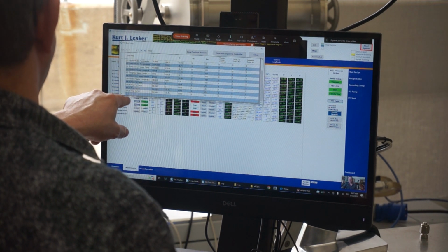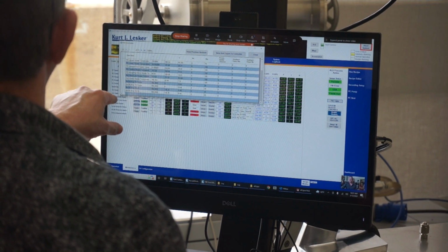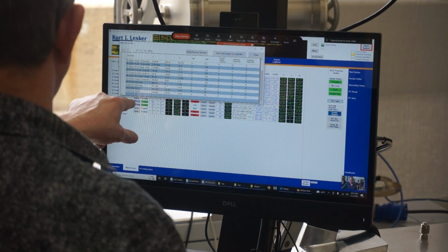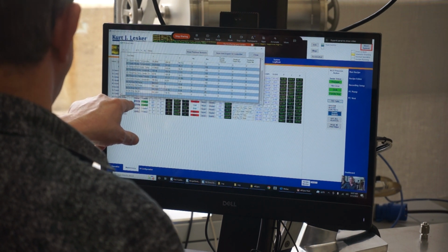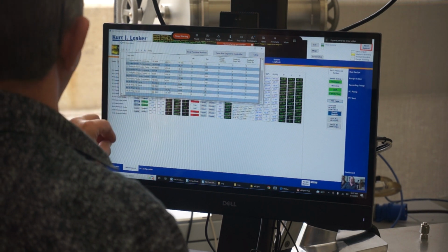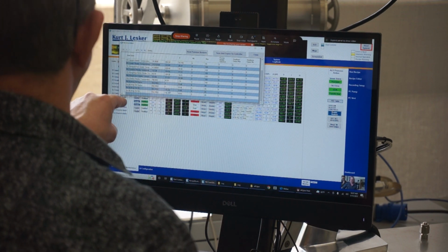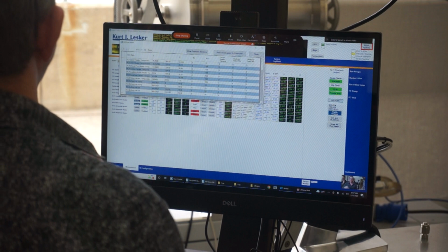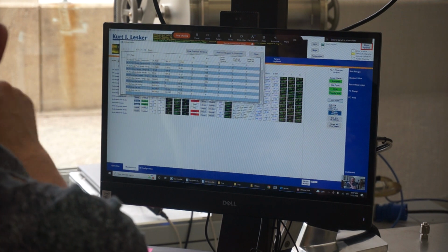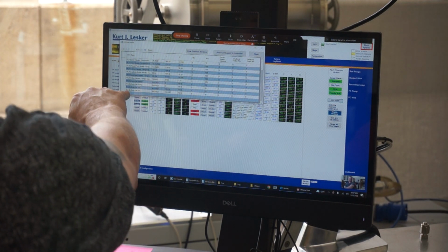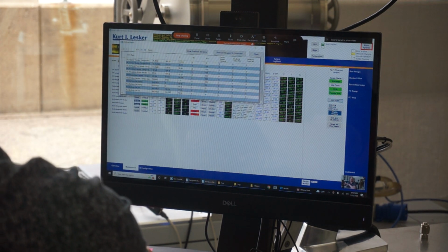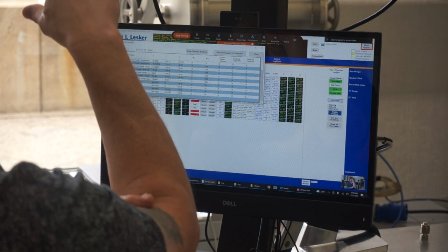If you choose to, we have ampule heating recipes. You'll have two different PID values. You have a heater ramp with no integral, and you'll have steady state, which has an integral. So whenever we're running an ampule heater recipe, not the normal heating recipe, if we were heating up zirconium to 75 degrees C, the recipe will say set point 75 degrees, input heater ramp, no I value. So that'll be almost linear whenever it's coming up if you look at it on a graph.